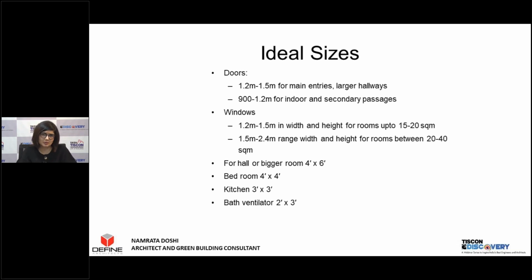If you're in the indoor space, like going from one room to another, like going from a kitchen to a living room, or going within the room to a bathroom, and you need to give a small passageway, usually a 900 passageway is enough. You can go a little lower if you like, but it's not recommended. A global standard would be 850 to 900. People do go lower in certain specific cases, although again not recommended.